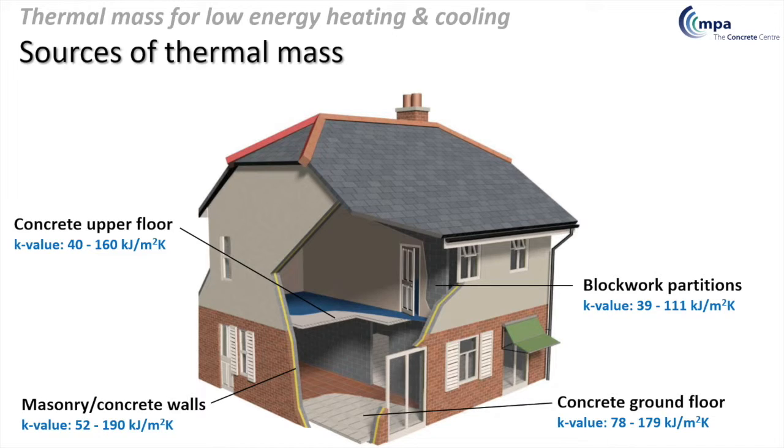And lots of thermal mass in concrete ground floors, which is a pretty standard feature in homes. And a tiled finish is fantastic. A little bit of mass in those, but like the wet plaster, it will conduct heat to and from the screed and the slab very effectively.